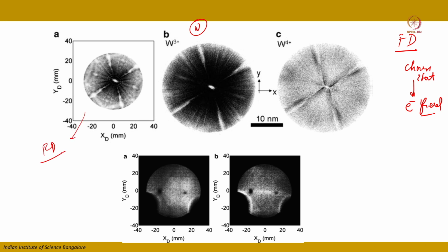You can see that by plotting W3+, the zone lines and also the pole have low density regions. While for tungsten 4+, you can see that near the zone lines, these tungsten 4+ ions get accumulated. These are nothing but trajectory aberrations, as tungsten 4+ needs higher potential. They have a higher evaporation field.